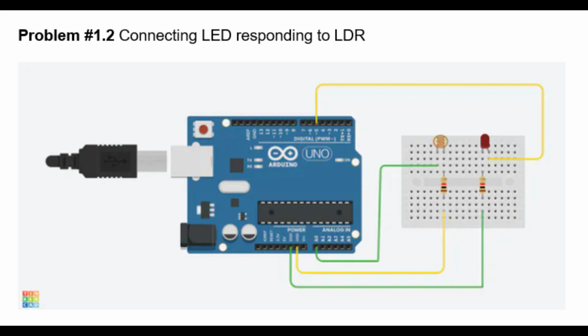Staying balanced. Understanding tilt sensors. These clever little devices contain a small conductive ball that rolls around within a chamber when tilted. This movement creates or breaks electrical connections, allowing us to detect changes in orientation.